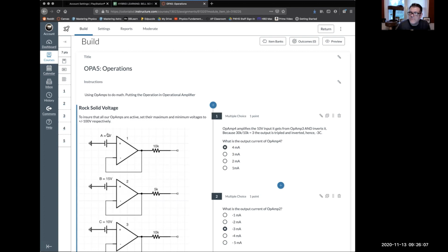Now this voltage source here, 5 volts, no matter what voltage it is, I mean a real voltage, like a battery, I plug a 9-volt battery to it and go into an op amp. The op amp will provide that voltage with no droop. It doesn't matter what load I put on. I'm going to get exactly 5 volts at the output, no matter what the load is. That's the advantage of using an op amp. If I take a 9-volt battery and I hook a motor to it, because of the impedance of the motor, the voltage on the battery droops. That's one of the things we talked about very, very early in the foundations unit. Well, these voltage supplies don't droop.